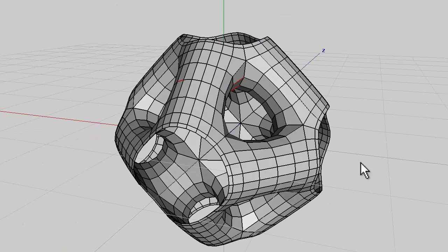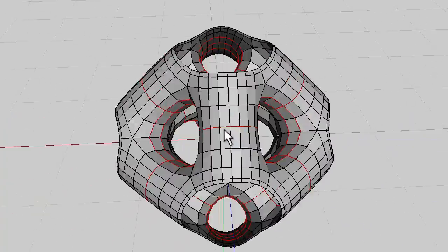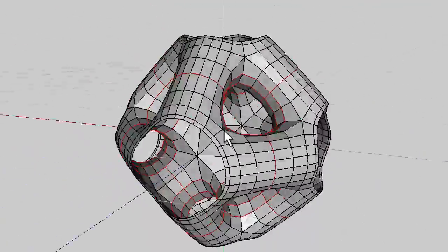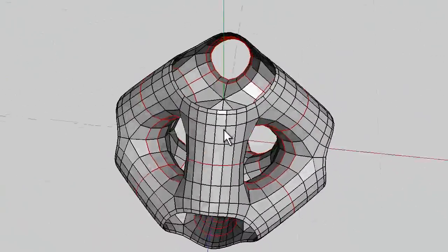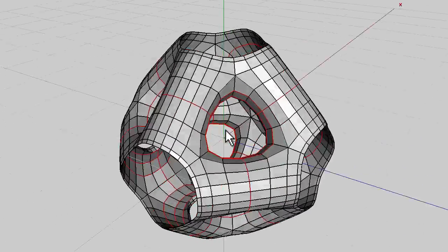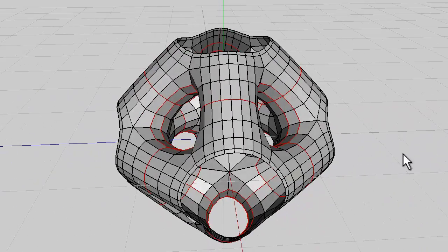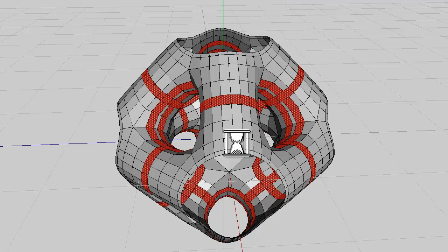So it gets a bit complicated again because I'm going to press I for identical. I'll press that a couple of times, then press loop, press that a couple of times, and see if these lines join up. You want it to be symmetrical ideally, just for the look of the thing. So I'm just having a look around this shape and see if all the lines have lined up, and you might want to do this a bit more carefully than I'm about to do, because I can always restart the video. And then right click and bevel, and just bevel them out a bit, your choice.